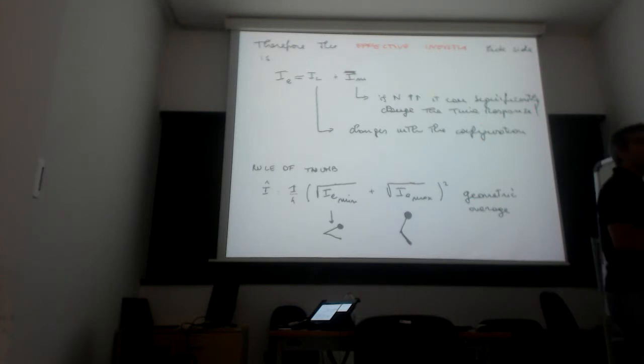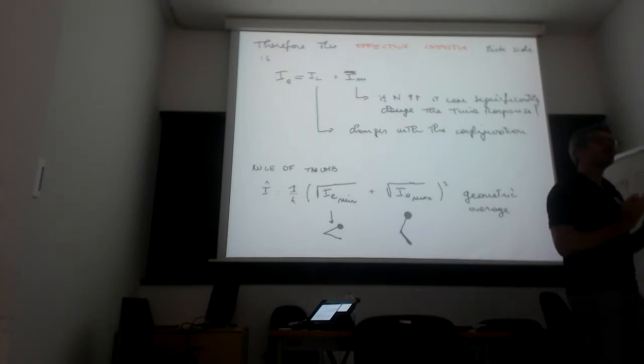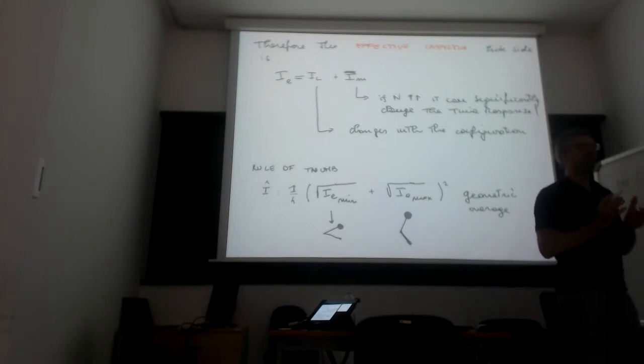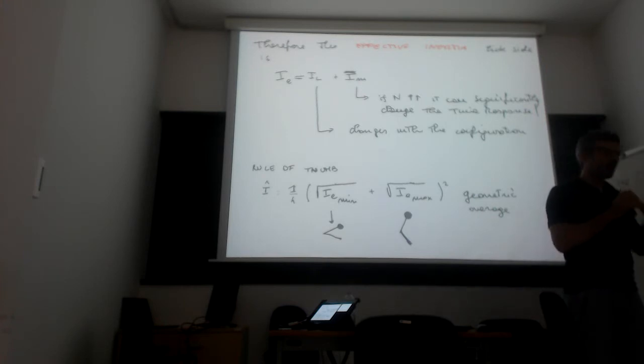They do overvoltage, so rather than use 48 volts to drive the motor, they spike up to 180 for a short amount of time. So ideally, you can extract any power from your motor. You can have a motor this size and ask it to deliver 3 kilowatts by increasing the voltage. What is the problem?